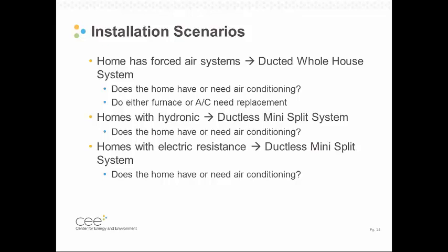And so that was really the scenario, the electric resistance scenario is really the one that we saw in this project. I will note that most of the installs for these ductless systems that happen in areas where natural gas is available is as sort of a supplemental heat or cooling to an area that they can't reach in a hydronic house. So if you put on a new addition and there's no central ductwork, you could stick one of these ductless systems in and it would be a pretty unique solution.